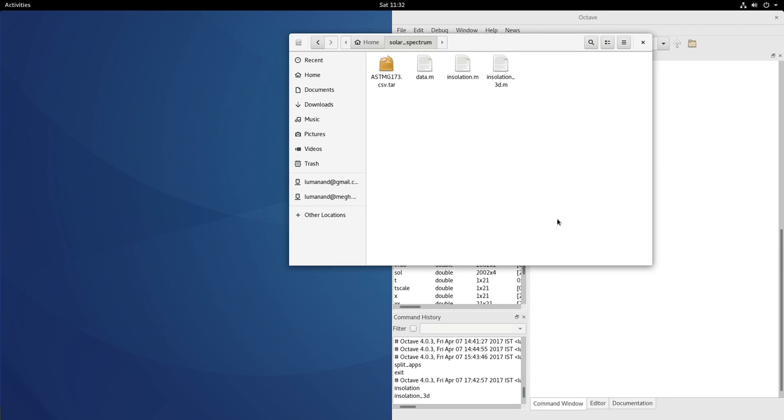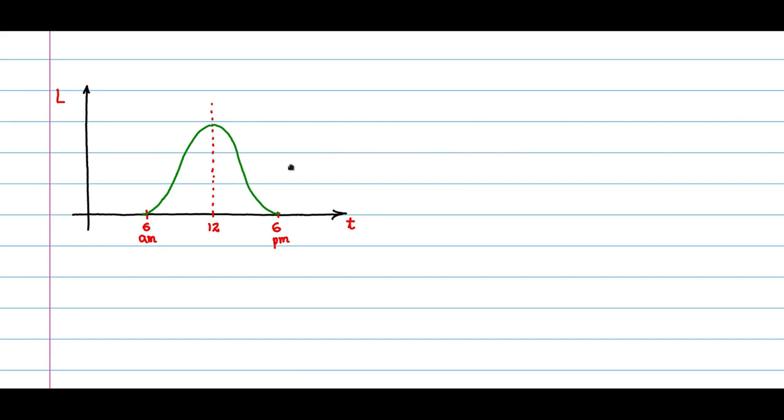you, the resource section. Once we know the daily insolation profile, we will be able to derive the solar photovoltaic panel requirement in terms of peak power. So let us put the insolation profile with respect to time that we just now saw on this screen. So we have the x-axis, which is the time axis, and the y-axis, which is the insolation in kilowatt per meter square, and we saw that this is the kind of profile that we get.